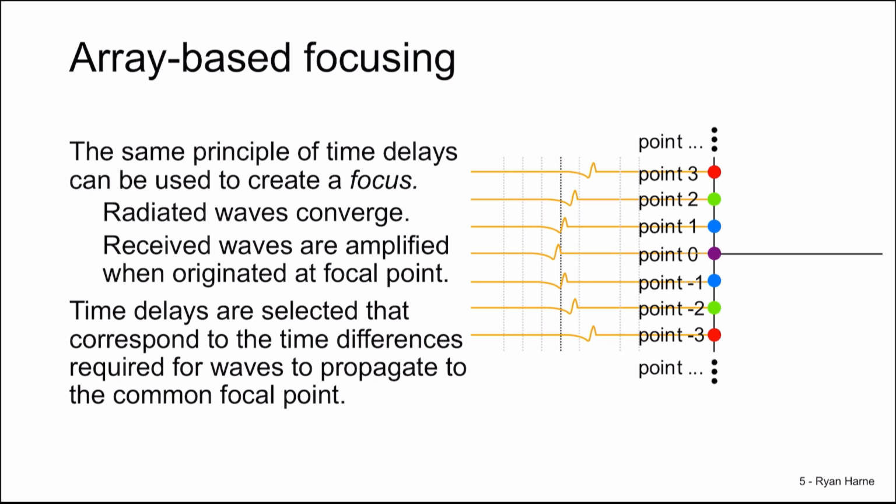the transducer. So by applying these representative time delays that you see here, we are able to counteract the fact that point sources 3 and -3 undertake longer travels for the waves from the point sources to the field point than the traveling distance from point source 2 and -2, which is still greater than point source 1 and -1, the distance between that source to the field point where we wish to focus.